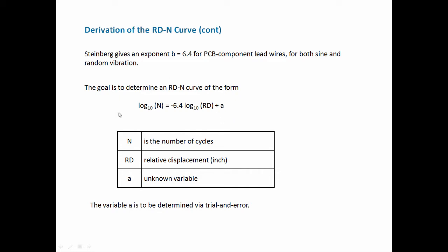So this is an important formula here, and we have the slope, and we know what it is at 20 million cycles. So if we set n equal to 20 million cycles, and do some more calculations and a few other things that I posted in the paper, eventually we can come up with what this A value should be, which is the unknown variable. The way I did it initially is I used a lot of trial and error numerical simulations, along with rainflow cycle counting.